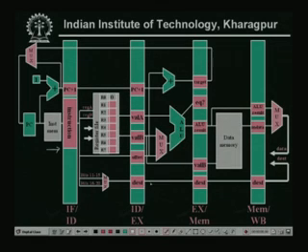Now, again, after decoding, it is determined what type of operation it is. So, it will be executed. Then memory is also accessed, the data is being taken from the data memory, and then there is a write back. That means the result is stored in the memory, or the data is updated in the memory. So, this is one stage.